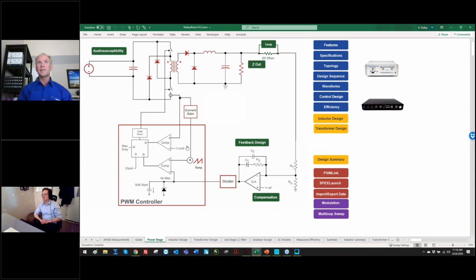To me, the big deal about power stage design these days, it's not about the controller. It's not even about the silicon anymore. If you want to buy a FET, there's 200 different FETs you can use. And at the end of the day, it doesn't change much of your power supply design. You just slap it on the board, you drive it, you put your heatsink on it, that's it.